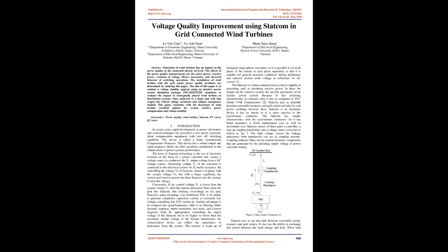Introduction. In recent years, rapid development in power electronics and control techniques has presented a new power electronic shunt compensation equipment with turn-off switching capability. The device is called a static synchronous compensator, Statcom. This device has a robust output and rapid response which can offer excellent contribution to the enhancement of power systems